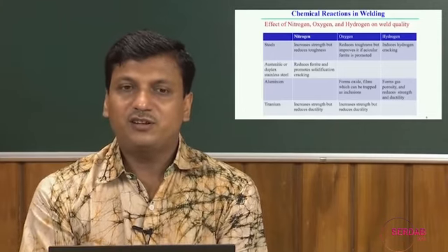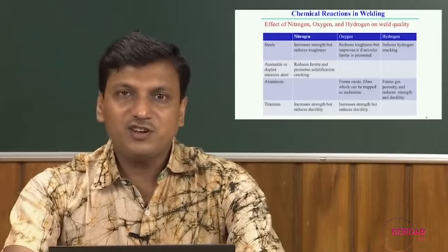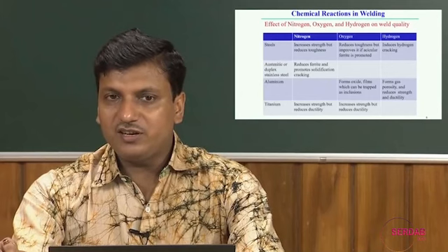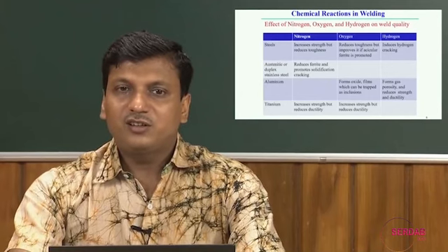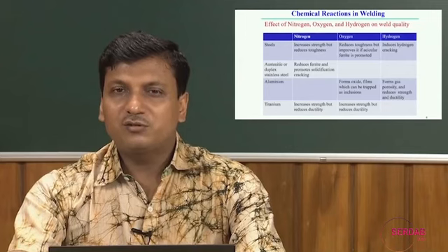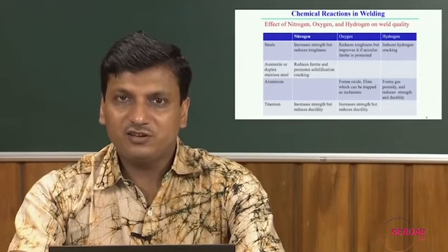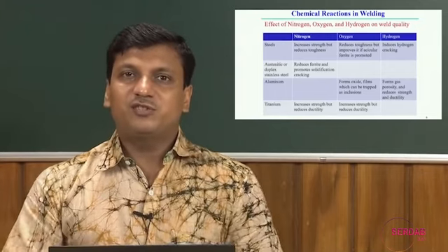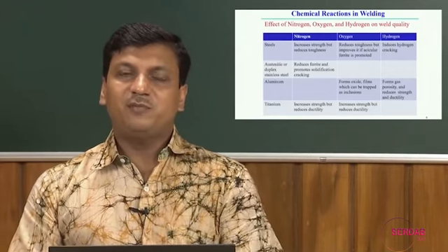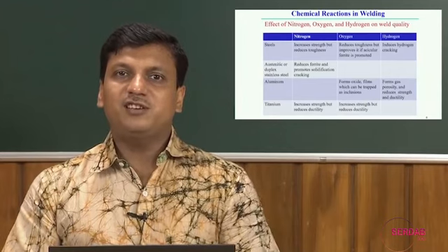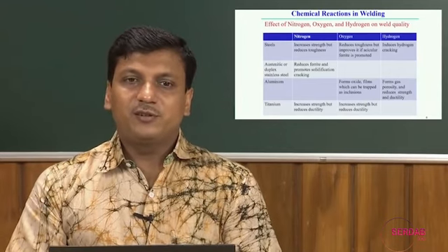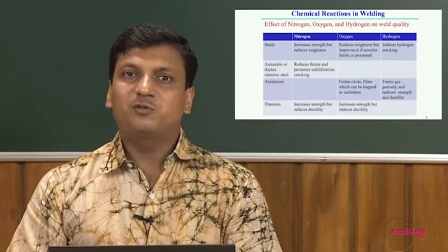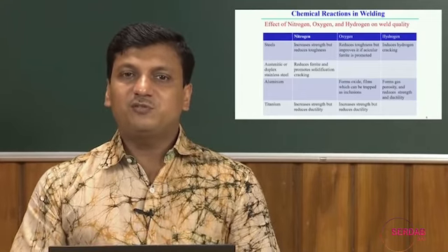And another material, specifically titanium. Titanium interacts with oxygen and mainly nitrogen. The presence of hydrogen also affects the joining of titanium and its alloys a little. That is a more serious problem in the welding of titanium, and very proper shielding is required to avoid interaction with the oxygen and nitrogen from the atmosphere.